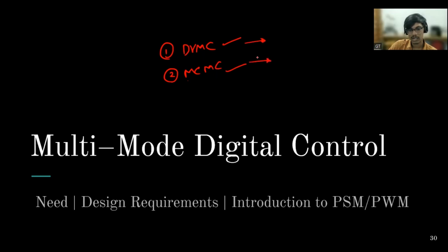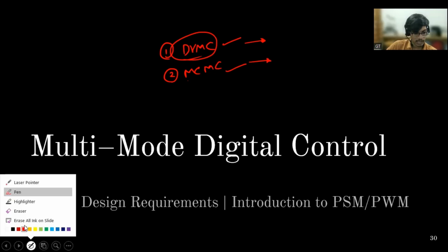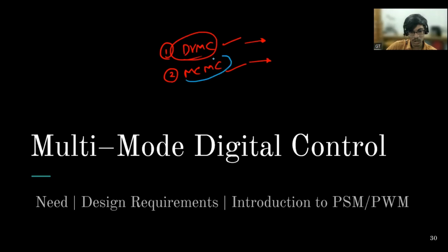So what are the advantages that we are getting using method 2 compared to method 1? And here we have seen the simulation results, and SAR has shown the hardware results. And in the other case, we had seen the hardware results of load current feed forward and its impact. We have seen that V naught overshoot, undershoot is minimal or close to 0 because of that load feed forward action. Now, this completes our voltage mode control and mixed signal current mode control.